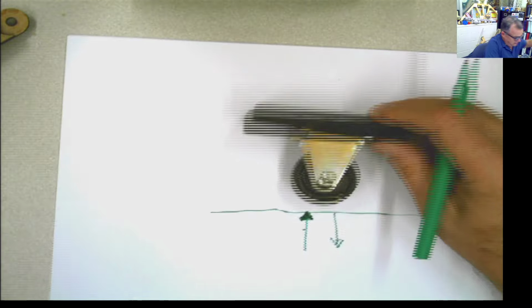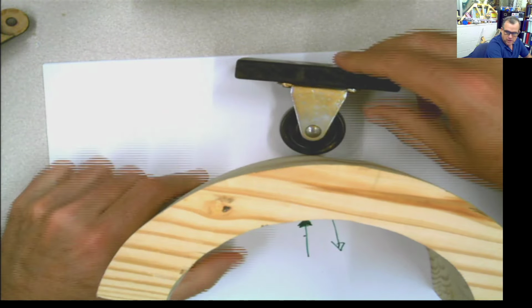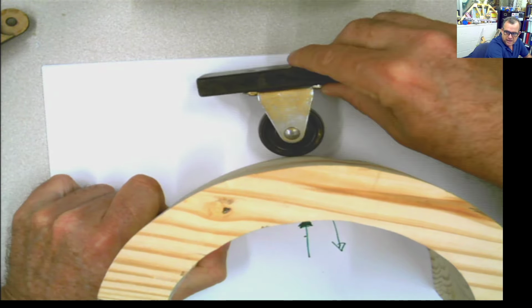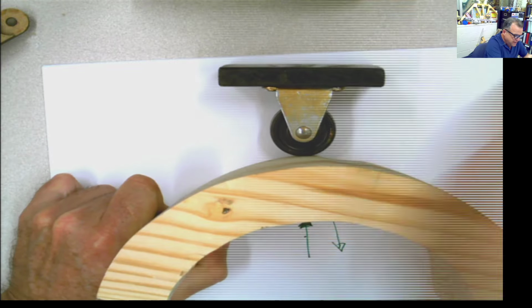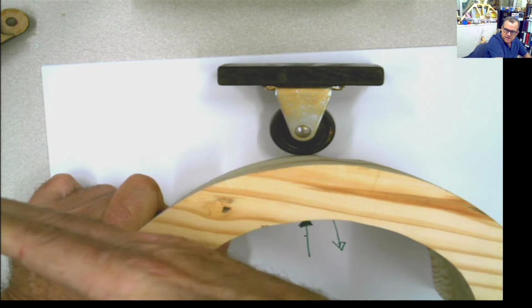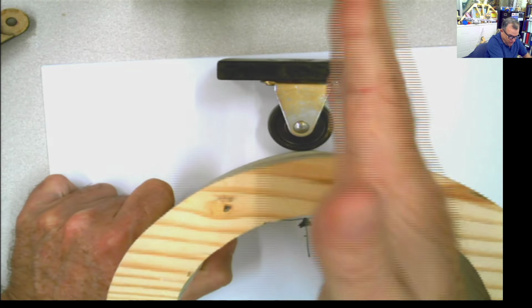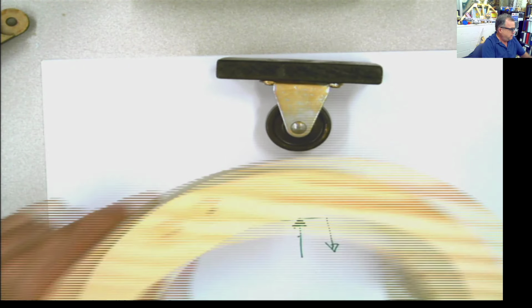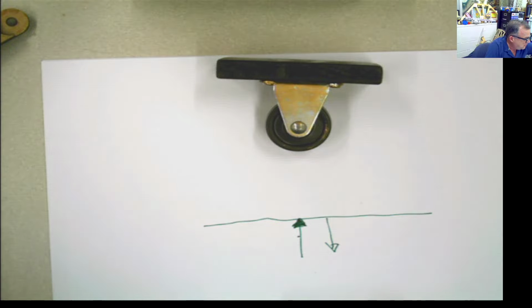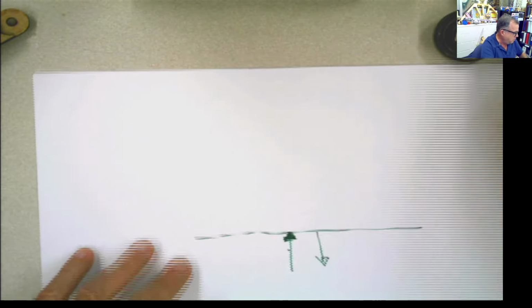Look at this. Now this is a surface that is curved. Well, this can move in that direction, however, it cannot go if I push it in. Once again, perpendicular, so in this case the reaction will be radial, or perpendicular to the tangent at any point. That will be the reaction provided by the roller. It's always perpendicular to the surface, always. Now there's another type of support which is called a pin.